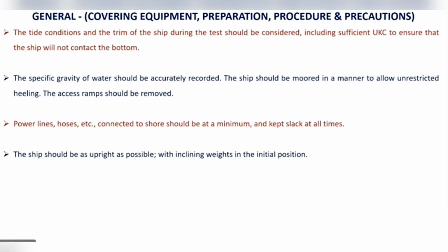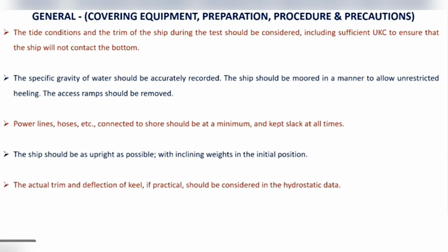How do you make sure she's upright? Yes, the pendulum will be one indicator; the other will be the drafts on port and starboard side, the actual trim, and the deflection of the keel. If practical, the deflection of the keel, which is hog or sag data, should be considered in the hydrostatic data. That means the draft survey, the way you do the draft survey. For getting the displacement, you should get the displacement from the tables as accurately as possible.